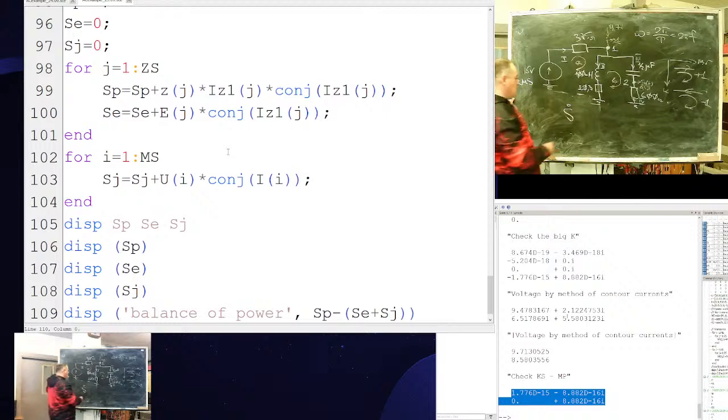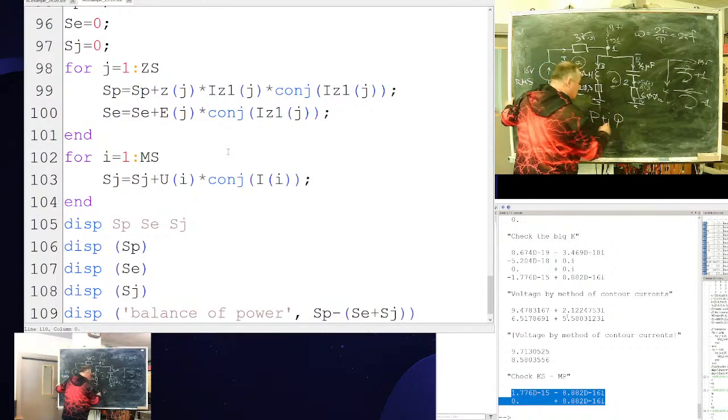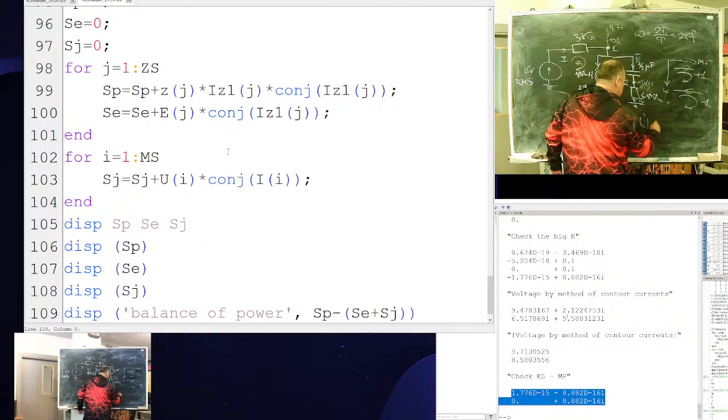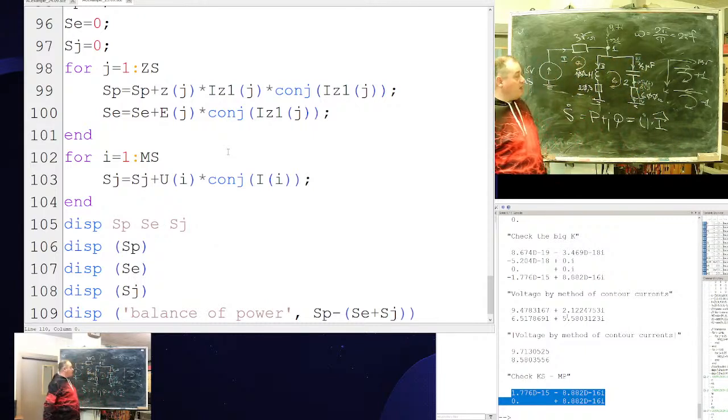Full power containing P plus imaginary reactive power can be defined as a complex value of voltage multiplied by the conjugate value of current. What's the conjugation? If you have some x with a point, its mirror will be a conjugation.